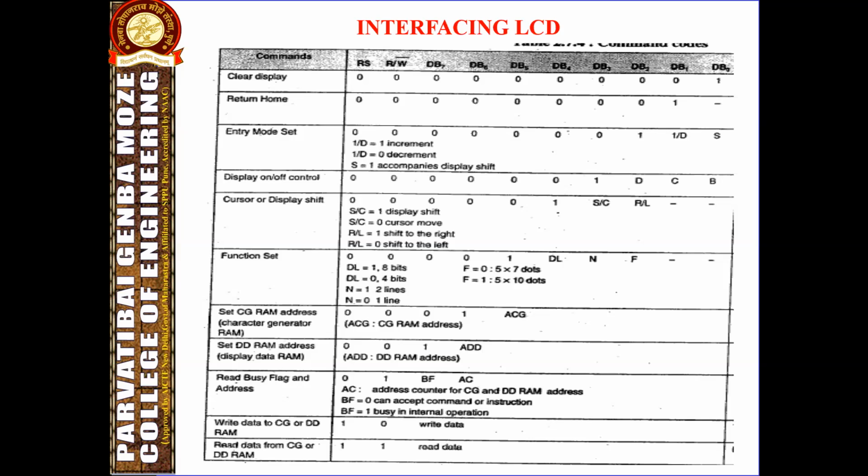Display on and off control 0, 0, 0, then D3. So when this bit is high, it sets the entire display on and off, cursor on and off, and blinks the cursor position character B. So this is the command. Like that we have to write the particular operation. There are particular codes, so we have to keep them in mind, and there are also subroutines, commands.